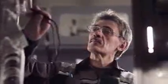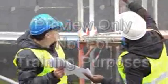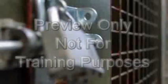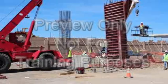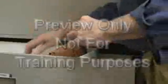Other required items include the maintenance of the MEWP, including inspections and repairs, the familiarization of the specific MEWP to be used by authorized operators, any local site requirements, and the means to protect against identified hazards in the operation area, monitoring of the work performance of the operator by a trained and qualified supervisor, prevention of unauthorized use of the MEWP, safety of all personnel not involved in the operation of the MEWP, and requirements for documentation of records.